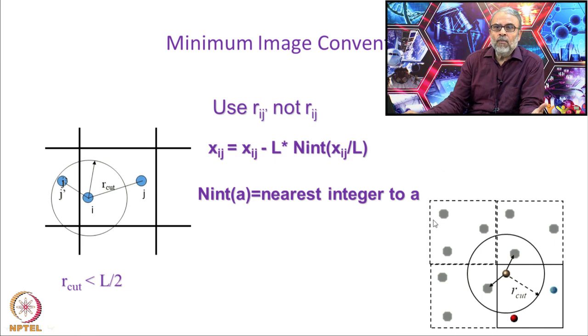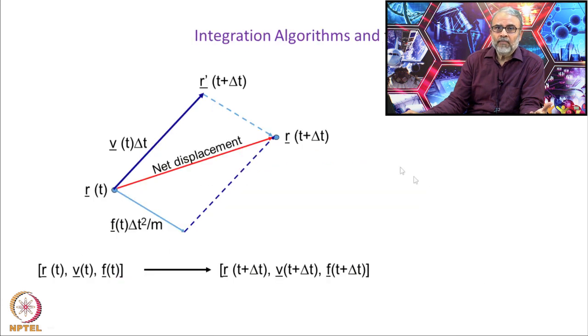The only problem would be if there are Coulombic interactions, this situation is not adequate, because in a Coulombic situation there are long range interactions. Therefore, I have to consider things like Ewald sum or reaction field. I have already mentioned this in my last class, and when you do GROMACS simulations, you will have more occasion to use these particular ways of doing things.